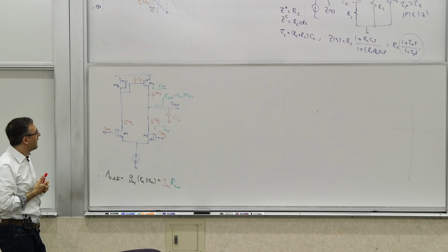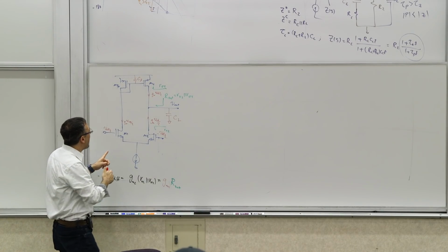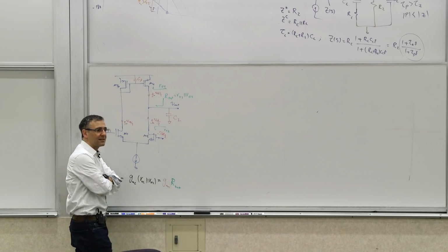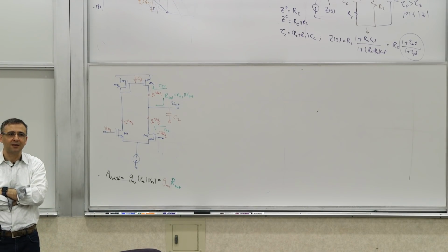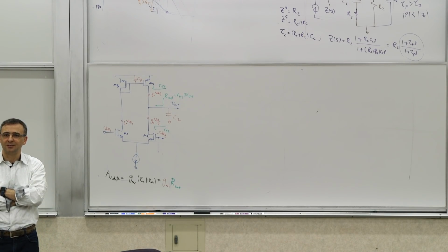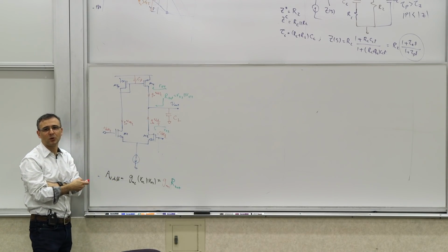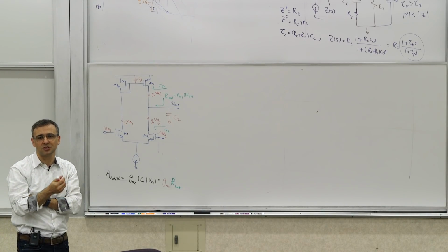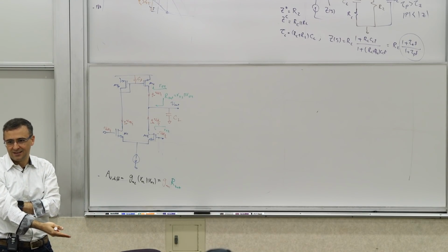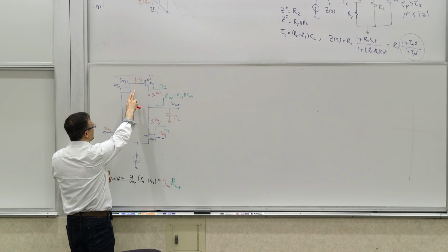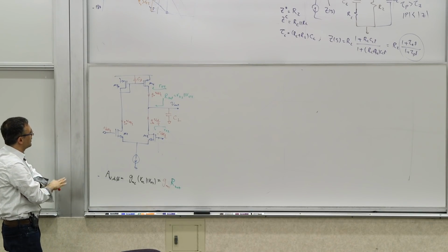Right? If there is that capacitor on that node, then there are two paths whose dynamics are not exactly the same. One of them is slower than the other one, if you think about it. Which one do you think is slower? This path is probably going to be slower. First of all, it's going through the PMOS, PFET. They have smaller gm, they have larger capacitance, and it's just got more stuff there. This path looks more straightforward. So this is probably the slower path, and this is the faster path. And we'll see what that does in a few minutes.